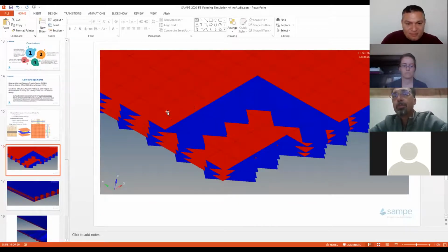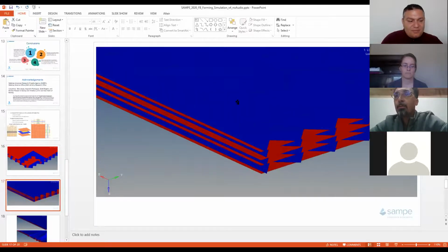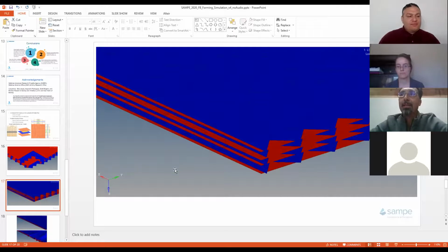If we consider a fabric material, what we decided to do, and that is a great example, you have your stacking sequence. Let's say the first layer is 0/90 degrees, the second plus or minus 45, the third plus or minus 45. That was a great intuition, because what we discovered at the end, you have a flat panel with all the stacking sequence in the pre-preg condition, where this is the material we see, and that mesh oriented in a very specific way allows the material card to obtain a better prediction in thermal performance. That's the idea, and I cannot tell you too many details because it's something kind of secret, but this is a nice recipe.